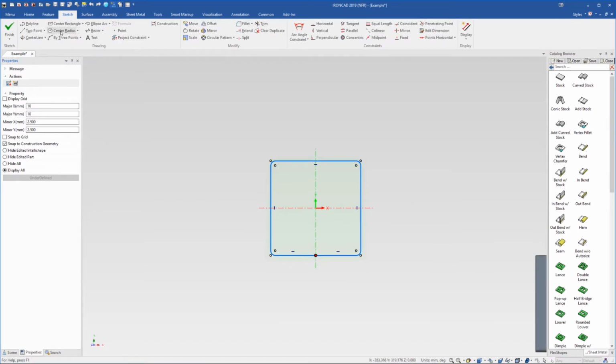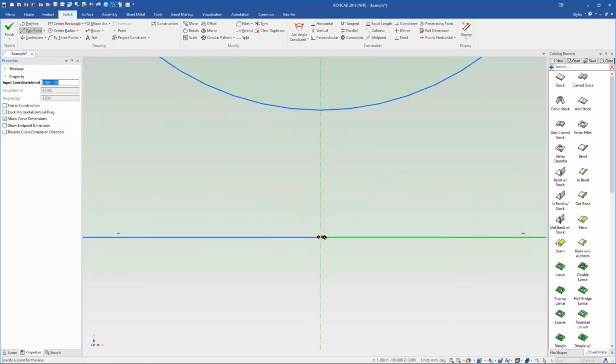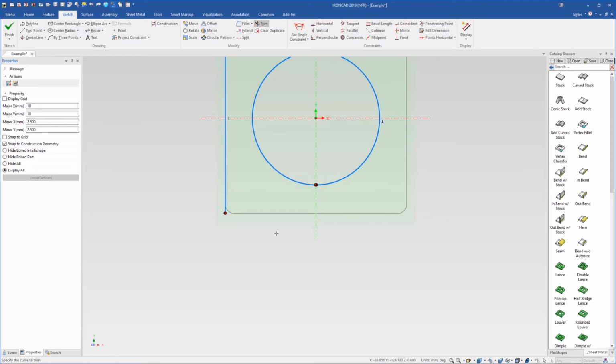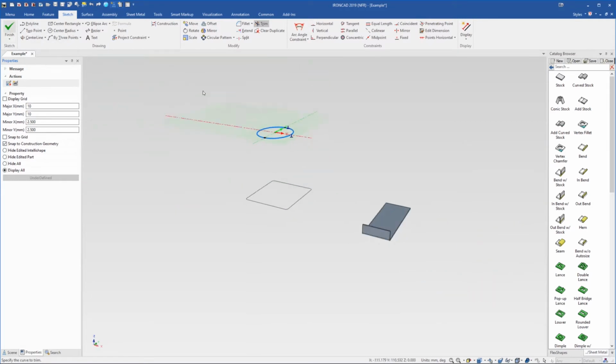Now what I'll do is draw a center radius circle. So I'll draw this here, and I'll choose what size I want it to be. In this case, I'm going to choose for it to have a 70mm radius, so I'll just press Tab key and then type 70 and hit enter. Next, I can go ahead and cut the same sort of cut I made earlier. So I'll do that by zooming in here and just drawing straight up lines from the other two lines, our 2 points we've got on our earlier shape. With that done, I can use the trim tool again, trim away everything we don't need, which is now all the lines in the model except our circle. Like so. Now I'll click OK to finish.